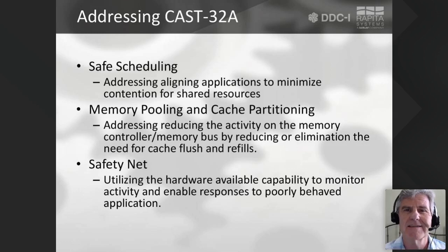CAST 32A indicates you must detect and control poorly behaved applications, while safety nets are a reactive, on-target, platform-dependent software strategy to meet that goal. These are based on hardware-software interfaces available for monitors in the system. Additionally, you're going to have to defend all of your mitigation strategies. Keep in mind, again, this is a collaborative effort. We will defend our products and our strategies in any audits that you encounter.